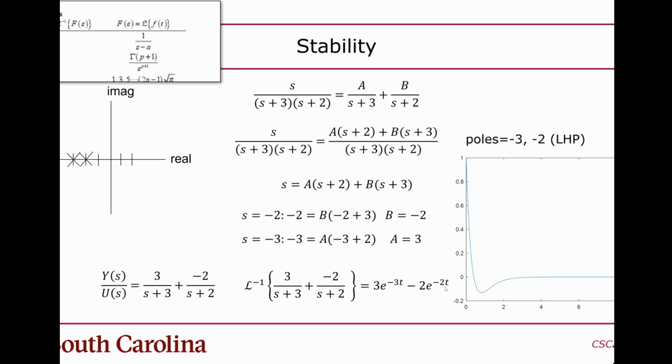You only have control of the transfer function of the controller, but you have to keep in mind that you would have to change the controller transfer function in a way that, when multiplied against the plant, and then of course also incorporated into the closed loop transfer function, the poles of the closed loop transfer function will be moved. So in practice, it's a little bit more indirect in the way that I'm doing it. And there are procedures to build controllers that basically allow you to change the pole locations of the complete closed loop transfer function. But again, we're not going to cover that.